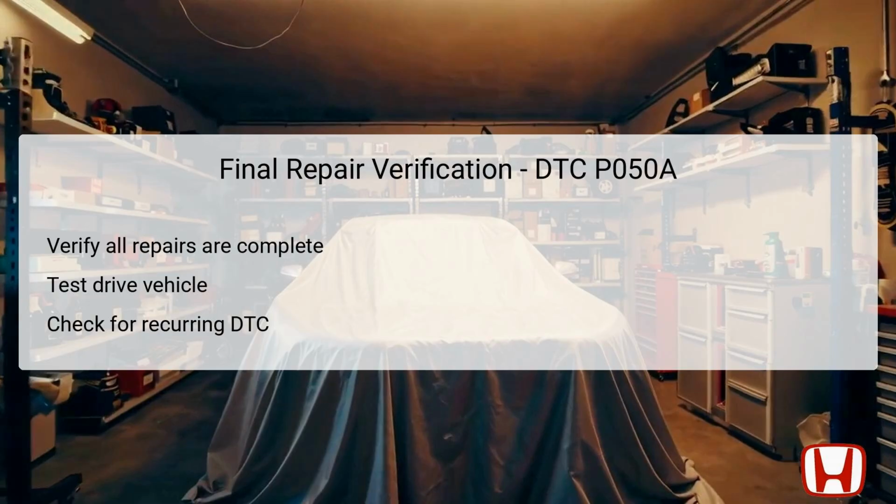During or after the test drive, perform a check for any recurring diagnostic trouble codes, DTCs, using the HDS. This final verification ensures the problem has been fully addressed and the vehicle returns to optimal performance without further issues. Documenting these observations is crucial for record-keeping and potential future references.